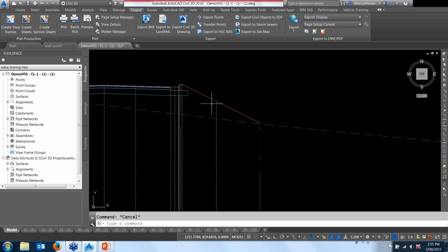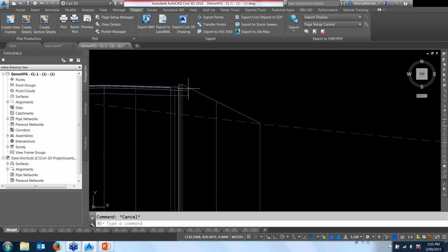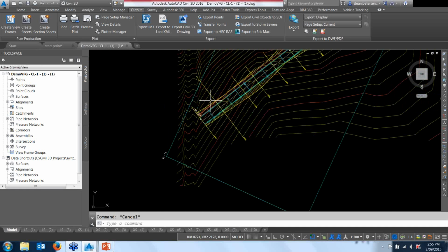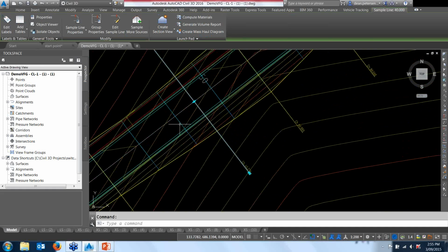These ordinate lines go in anywhere that there is a crossing triangle in that top surface. And because I have moved, go back to the plan view here, that sample line off one of these blue frequency lines in the corridor, we end up with crossing extra triangulations in between there. When you actually make a surface, it triangulates between these blue lines.